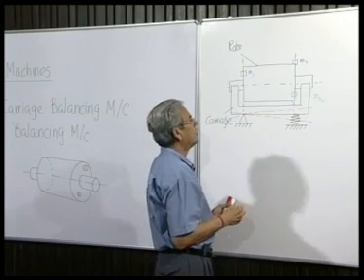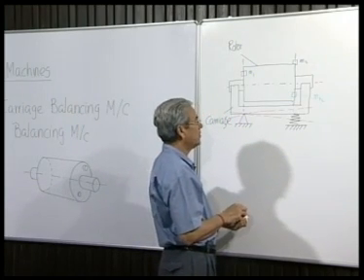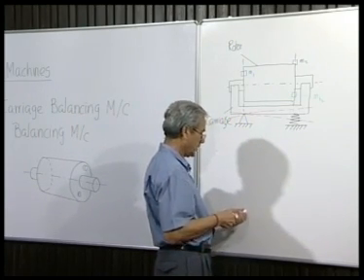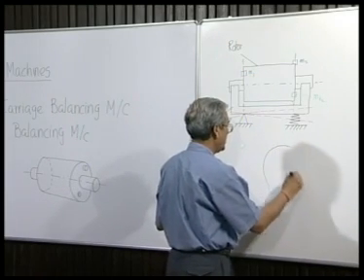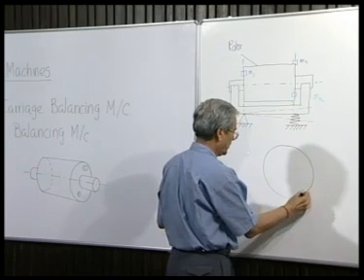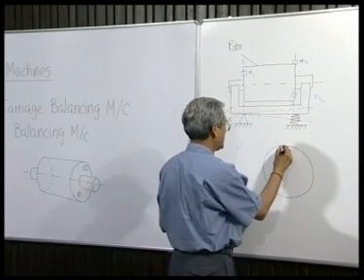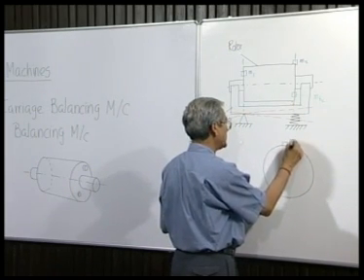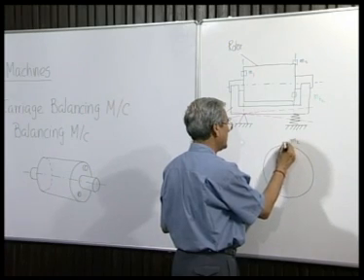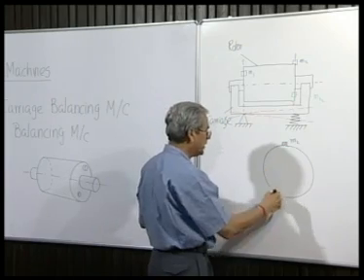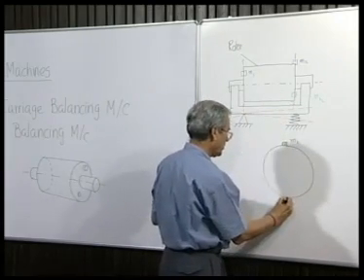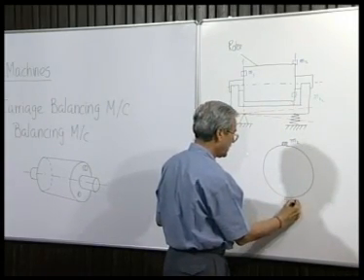That is the situation where we may consider that this trial mass is approximately opposite to m2. It can be explained this way: if m2 is this, then the location where the trial mass mt2 will produce minimum vibration will have to be here,